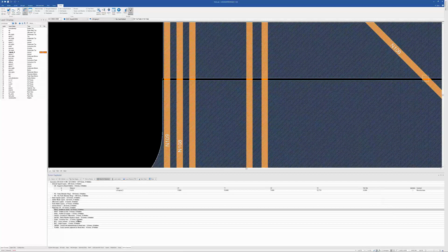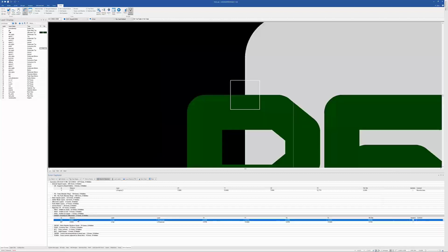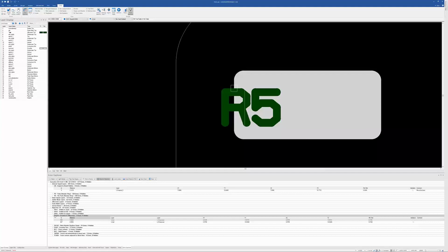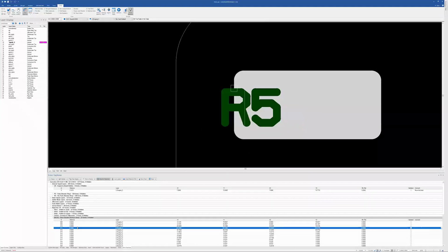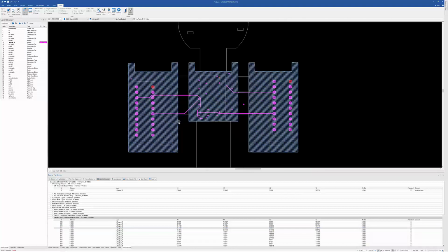Some cover lay to solder mask issues, or cover lay to silkscreen issues, similar to a solder mask to silkscreen issue. Data outside of stack-up zones, we've already seen some examples of that. Here's some more. You can't really have data outside these zones because they don't exist. If that was on my flex layers, yes, but not on my rigid layers.